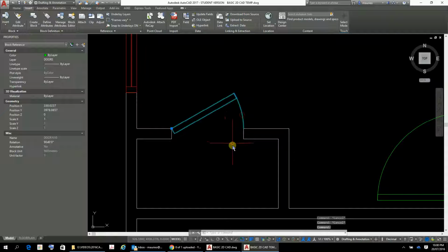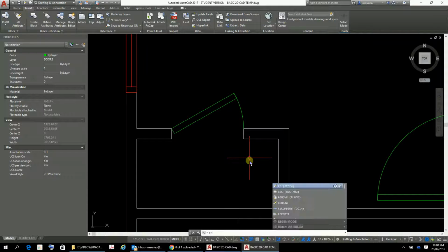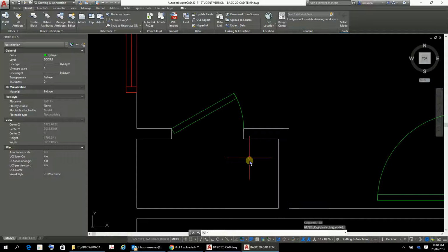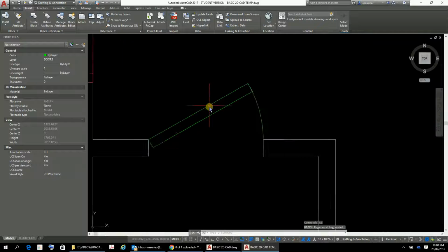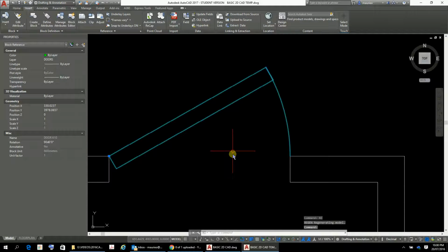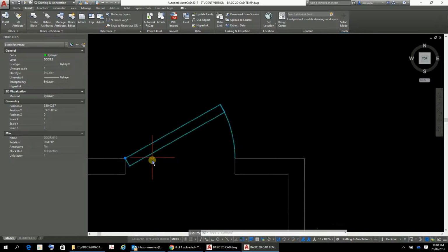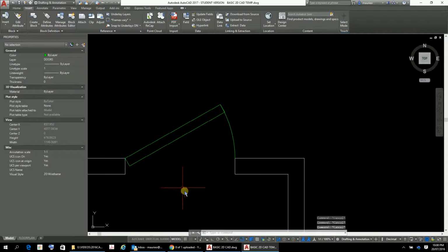And there it is in the doors layer, and that's our little 610 door there. You can see all those little lines through there. That's from some stuff that was going on. Sometimes you get that if you push RE for regenerate, it just redraws, and I was hoping that would do it, but it doesn't seem to want to. I don't know why it's got those funny little chunky lines in there. We'll have to see what transpires with that.